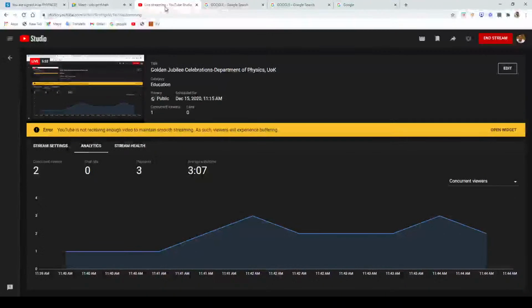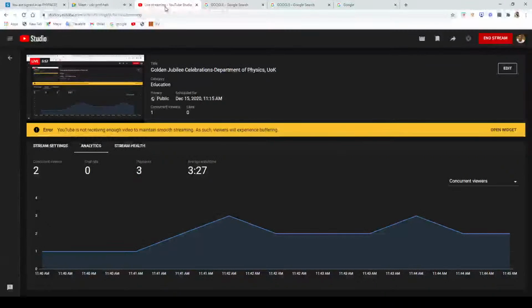Only thing is the temperature at which we deposit tubes, for example, carbon tubes, is very high, and it's a very highly supersaturated solution. So the carbon tubes are really created out of a solution. They are ejected from a supersaturated solution. So the mechanism of forming carbon nanotubes is slightly different from that of, say, vapor to liquid directly or vapor to solid directly.